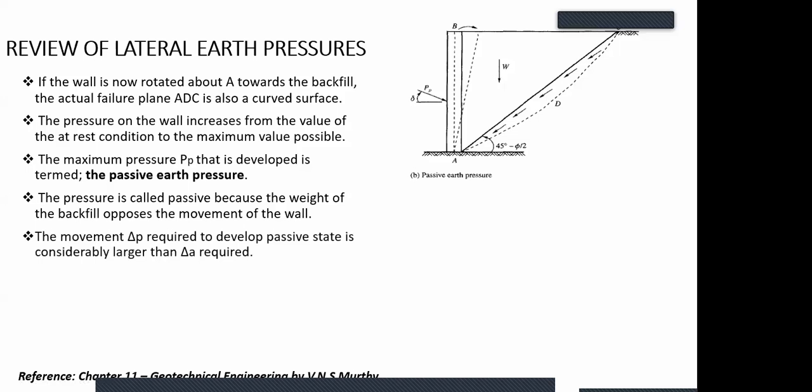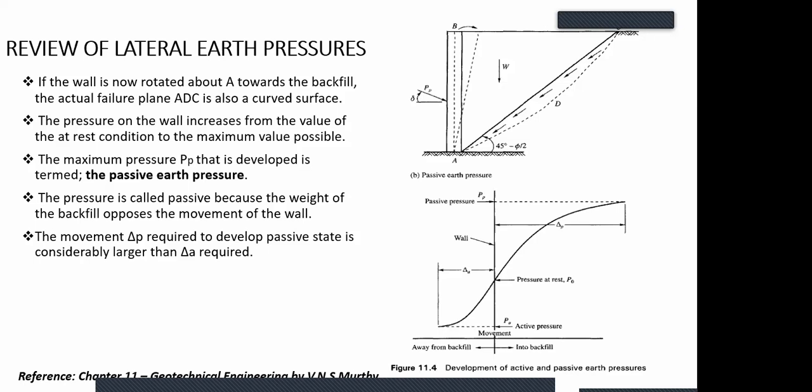And I said that it will take considerably larger displacement or larger effort to get to your passive, because something is trying to push you away, but you want to move opposite to the direction of what is pushing you away. So it's going to take longer effort for you to actually achieve that. And that's why I said that the displacement of your passive pressure is far, far greater than the displacement of your active pressure. I hope this is clear, sir.